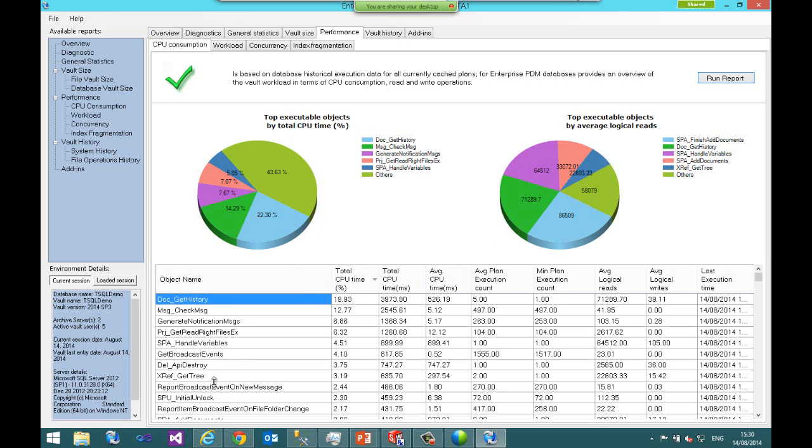Now, on a production environment that is using SolidWorks assemblies, let's say medium and large assemblies, more than 50% of the CPU will be xref-get3, because basically it's used during file references. So if you see this consuming more than 50%, it's not something strange. It's normal because we read file references when we do checkout, check-in, get references, change state, and so on. Actually, not during check-in. During check-in we have build tree, but all the others do apply.